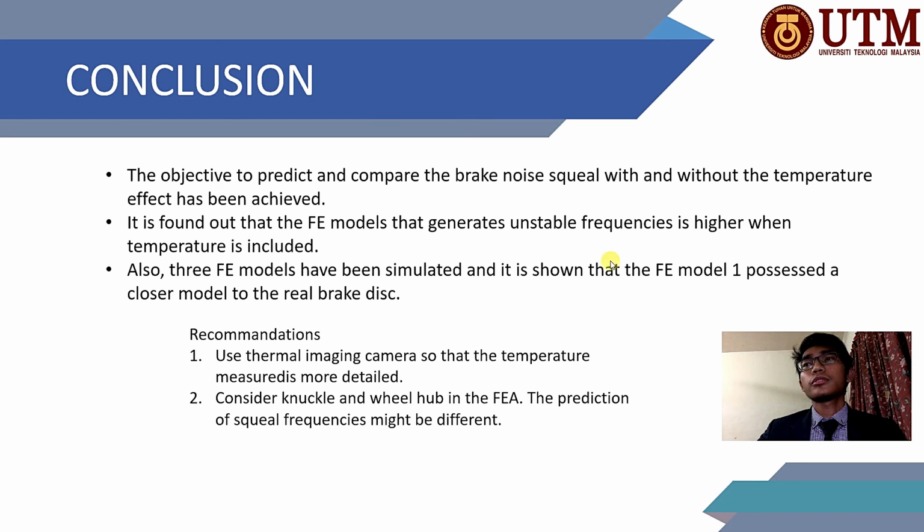So in conclusion, the objective to predict and compare the brake noise with and without the temperature effect has been achieved, and it is found out that the FE model that generates unstable frequencies is higher when temperature is included. Also, 3 FE models have been simulated, and it is shown that FE model 1, which is the model that included all the temperature of the component, possesses a closer model to the real brake disc.